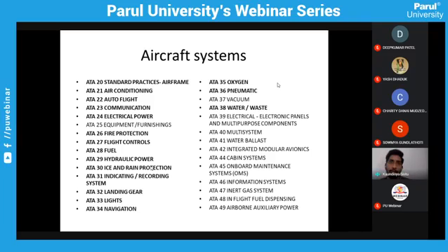The high spool continues from 5 to 10 bar, increasing the pressure more. During the start of the engine, the LPC, low pressure compressor, provides the air for the air conditioning, and the high pressure compressor provides it later, after about 30% of the ideal RPM is reached.